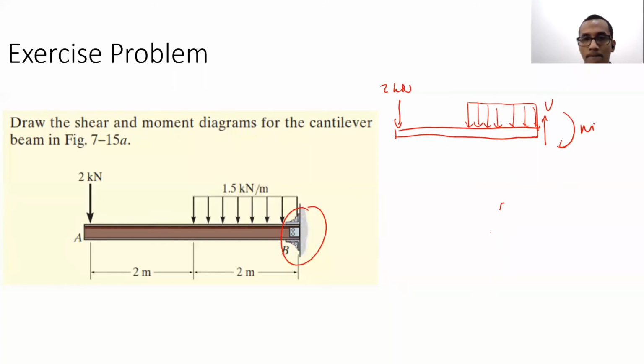Yes, sir. Now, try to take a look at the discontinuity that I talked about just now. Discontinuity will be there because of a concentrated load, a concentrated moment, and the start of the distributed force.